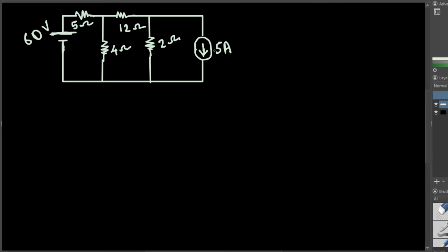And when we remove the current source, it's going to become an open circuit. So we are going to have an open circuit like this. So it's going to be removed right here. There's no current flow. Now let's actually do that. Let's divide this one into two. So this one, if I apply superposition theorem, it's going to look like this.